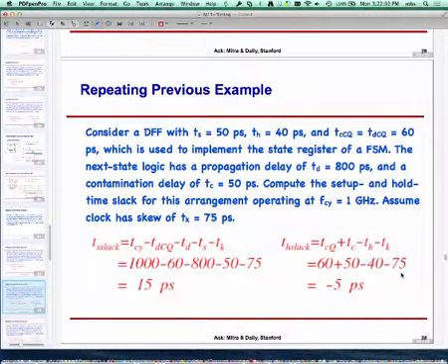How do we know whether to add or subtract skew in these two cases? In this case we are looking at the worst case. Oftentimes when they give the skew, like in this example, what they're saying is if I look at two flip-flops, one may receive the edge up to 75 picoseconds earlier sometimes, or may receive it up to 75 picoseconds later at other times. So the skew is not in one direction in this example, which is why we took the worst case for both.